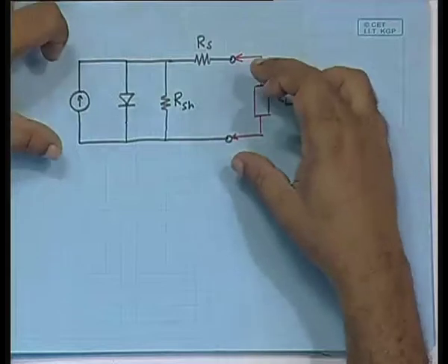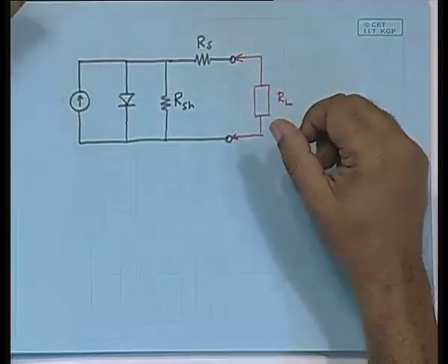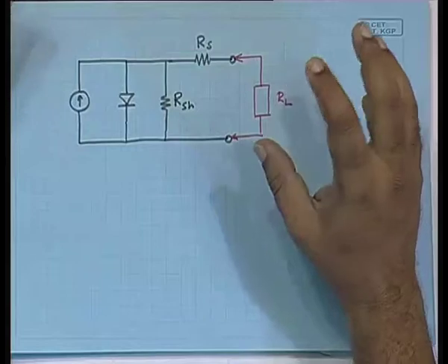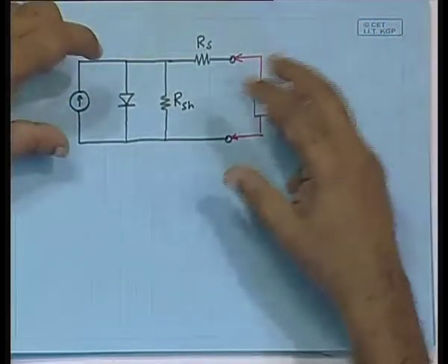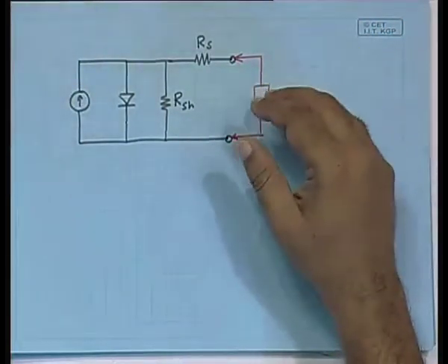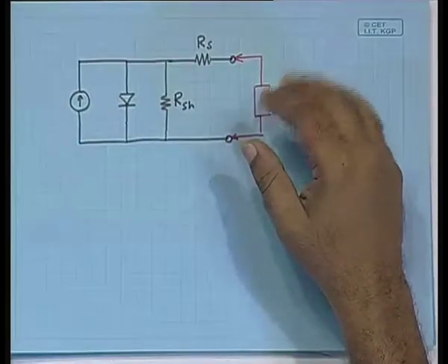Mostly these photovoltaic panels, I will be using the photovoltaic cell and the photovoltaic panel in both of the cases. A cell means a single cell, and since a single cell produces a voltage something like 0.8 volts, which is not useful for most purposes. So, a large number of cells are connected in series, normally something like 30 to 36 are connected in series to produce a voltage like 24 volts. That is a panel. So, when I refer to it as a panel, it is a collection of such cells.